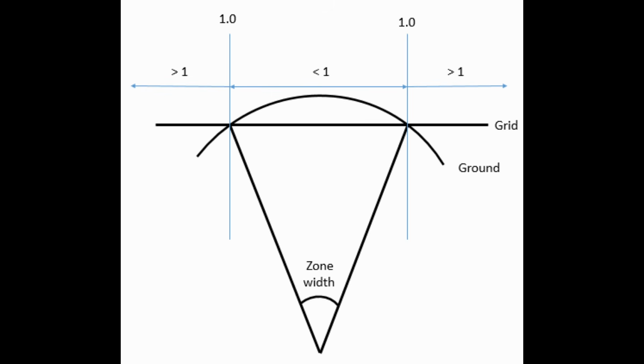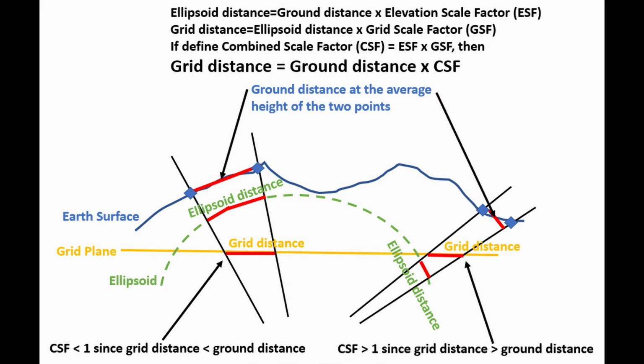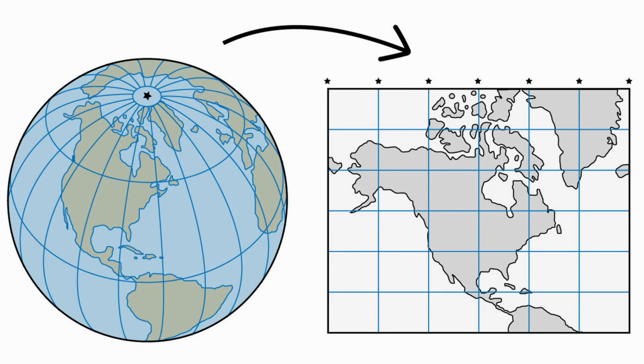Because the mapping projections we use for grid coordinates are usually conformal, which basically means the angular relationship between points is preserved over a small area, if we appropriately handle the linear distortion via a scale factor, we are able to effectively translate our geographic coordinates, which are what GNSS likes, to ground-based coordinates, which we like.